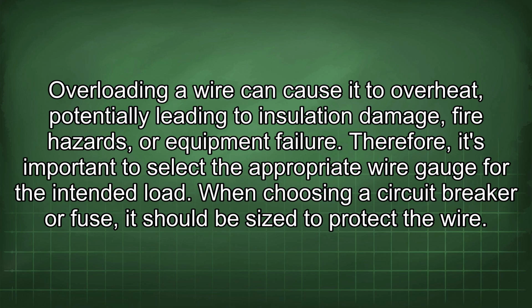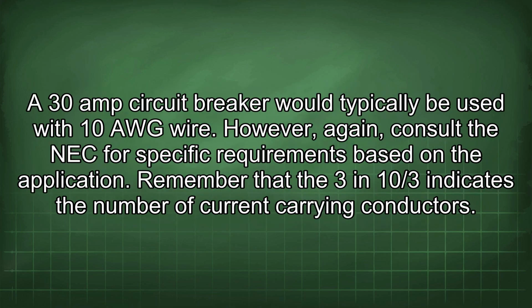When choosing a circuit breaker or fuse, it should be sized to protect the wire. A 30 amp circuit breaker would typically be used with 10 AWG wire. However, again, consult the NEC for specific requirements based on the application.